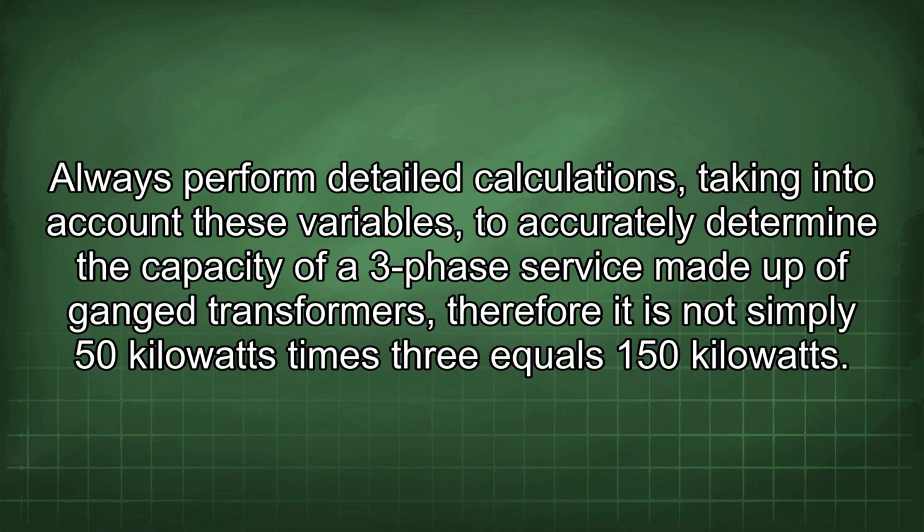Always perform detailed calculations taking into account these variables to accurately determine the capacity of a three-phase service made up of three transformers. Therefore, it is not simply 50 kilowatts times 3 equals 150 kilowatts.